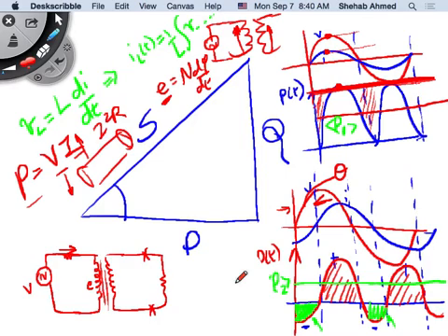But if you put a second winding, what's going to happen? That flux in the core will also link that second winding, creating a voltage, right? So this is how the transformer works. If you create that voltage, now you have E here, and let's say a 1-to-1 turns ratio, so you have an E here as well, right? So if you have some impedance, and this is an open circuit here, then some current is going to flow to create this flux, which creates these E's.